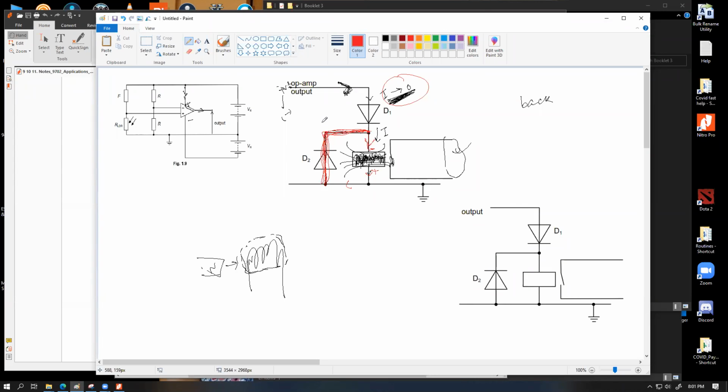Now you might wonder, well, fine, a single piece of wire should essentially suffice. What's the whole deal to give another diode over here? The diode is pretty important because the entire idea of this whole shebang was to make sure that this switch should work exclusively for the positive output, not for the negative output. So this is what we want to achieve.